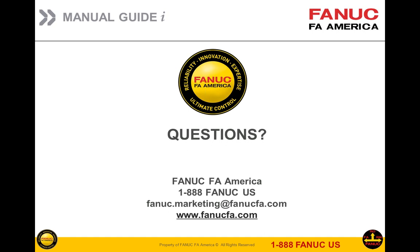Another basic question here from the audience. Is the D offset 1/2 the tool? Now, assuming that's the diameter offset, 1/2 the tool diameter. Yeah, it's the radius of the tool. Yeah, it's radius, okay. I know I kept saying diameter, but that's just the way I reference the D word in my mind. I always say diameter, but actually I mean the radius on a mill.